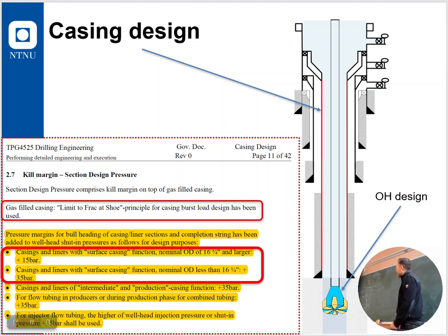And what's going to happen in this annulus, gas gradients and so on, you will not see a higher pressure between these two than the fracturing gradient in this annulus, because you have not cemented into the casing. All right. So basically, this is how you think about well integrity and integrity for these casings, starting from already this point.